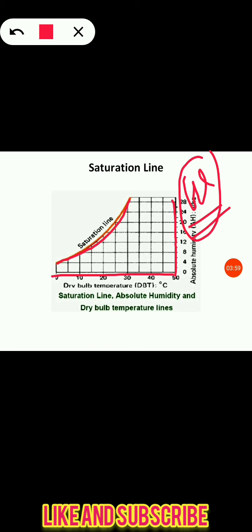Now suppose there is air at 35 degree dry bulb temperature and 30 degree wet bulb temperature. From this you can find the dew point temperature as well as the specific humidity. If you draw a line from this point to the right side, you will get the specific humidity, and if you draw a line to the left side, you will get the dew point temperature for that particular condition.